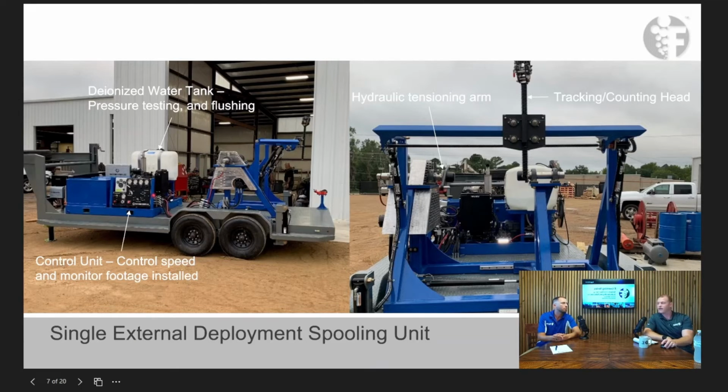If it pressures up higher than it should, usually 500 pounds, 1,000 pounds, depending on what your check valve is set at, that usually means there's something wrong.